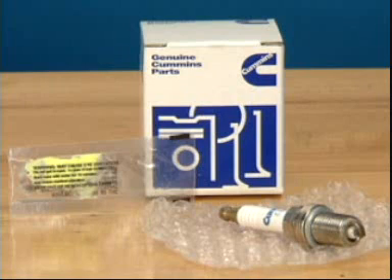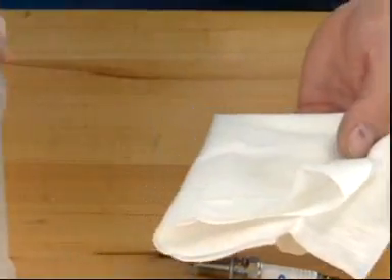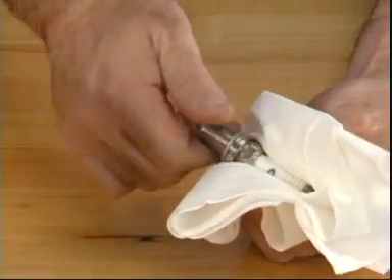Spark plug life is largely dependent on the cleanliness of the porcelain insulator. Dirt, oil, and fingerprints reduce the seal strength between the spark plug boot and the porcelain, causing reduced plug life. Do not touch the porcelain insulator of the spark plug. Use rubbing alcohol and a lint-free cloth to clean the spark plug porcelain and magnetic spark plug socket before installing the spark plugs.